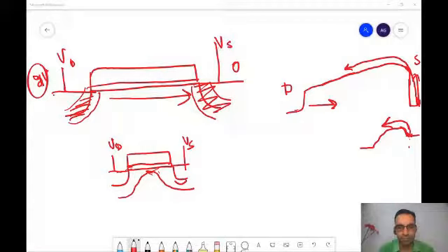Sir, is this some energy barrier or some physical barrier due to depletion? This is the energy, this is the conduction band that I have shown. Here we assume that the depletion of drain and the source in long channel have reached their maximum depth, however much VD is raised in long channel. So the source and drain junction, this is the junction property. We're not talking about the gate over here. No, sir, I am talking about this junction only.